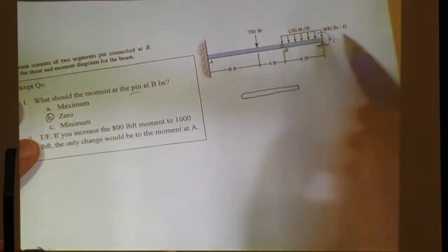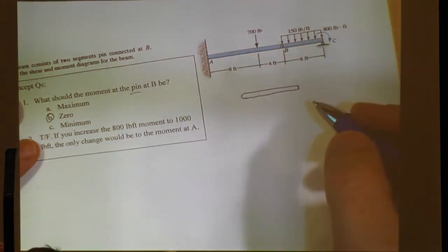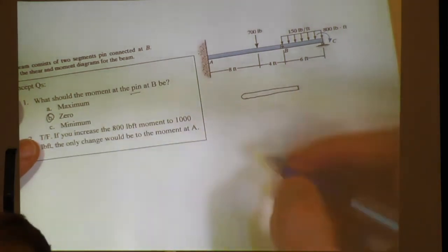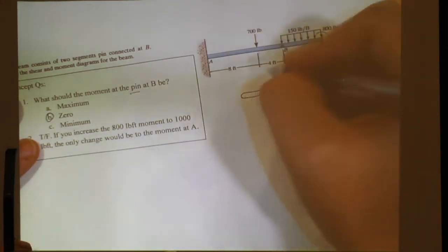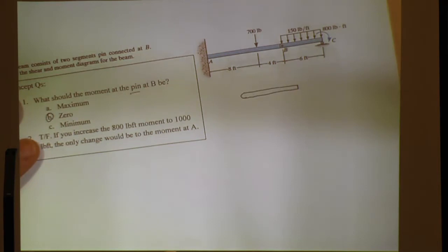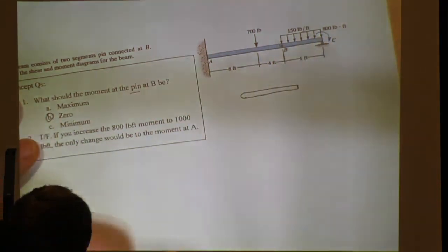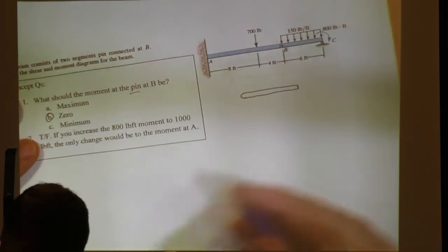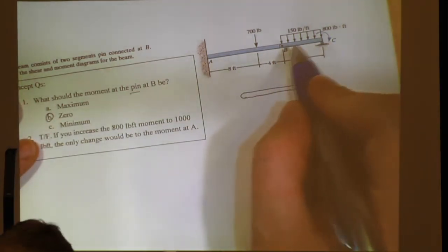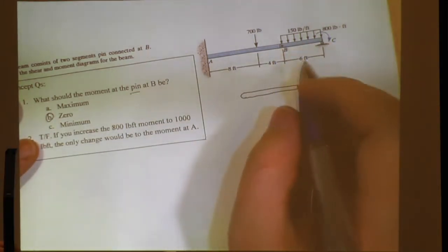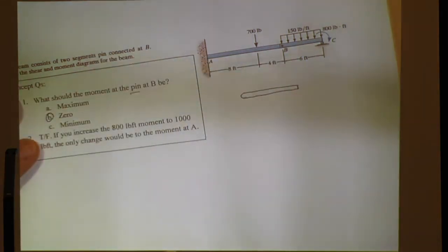All right, and what do we do with distributed loads? We make it one force to get the reaction forces. And remember, when you're doing your shear and moment diagrams, be sure to leave this as a distributed force once you start drawing your shear and moment diagram. It has to stay a distributed force. If you're confused about that, we'll go through it in a minute when we get there, and you'll see why.